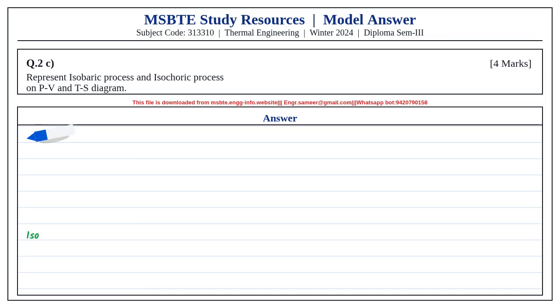For steam turbine, heat loss, potential energy change and kinetic energy change are usually neglected. Therefore, turbine work is H1 minus H2. For steam boiler, no shaft work is done and changes in kinetic and potential energy are neglected. Therefore, heat supplied is H2 minus H1 and for mass flow rate M, Q is equal to M into H2 minus H1.